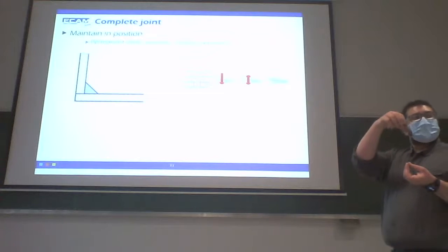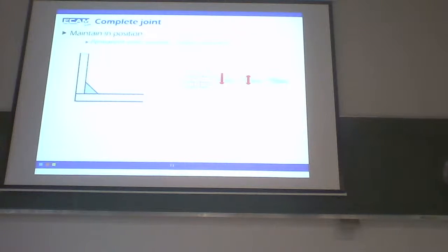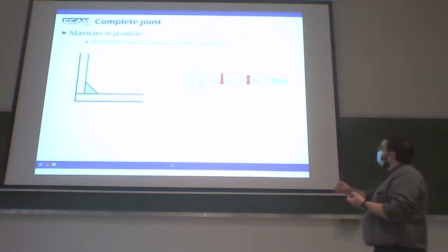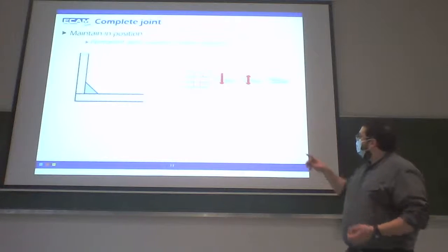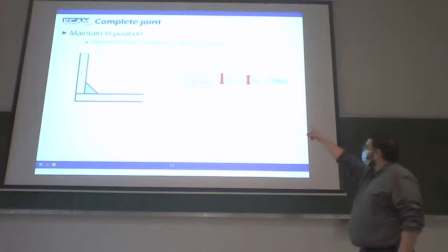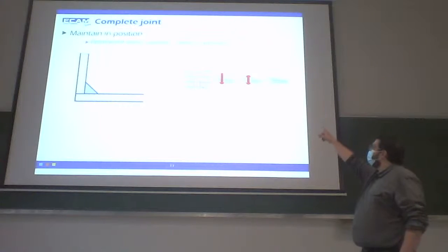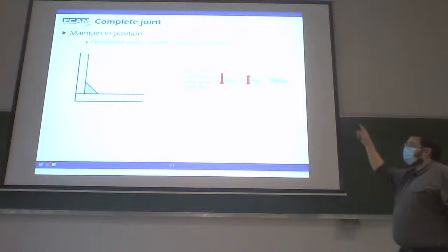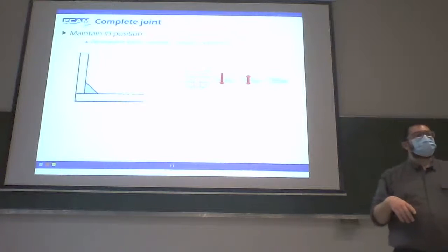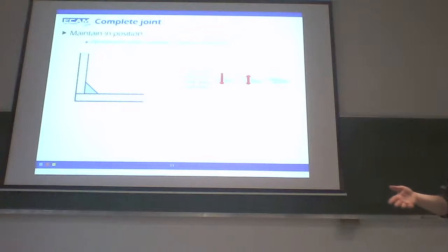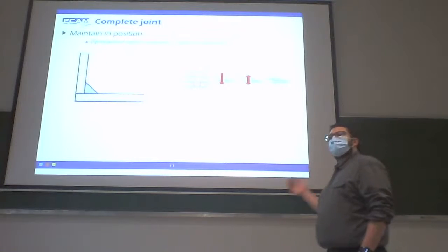And then we will deform, modify the shape of this part, to realize a complete joint between them. Here's the example. Here you see the first rivet in red is before deformation. We deform it by a matrix and realize a complete joint between the different parts. If you want to disassemble two parts fixed by riveting, we need to break the rivet.